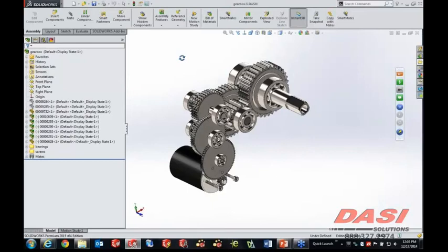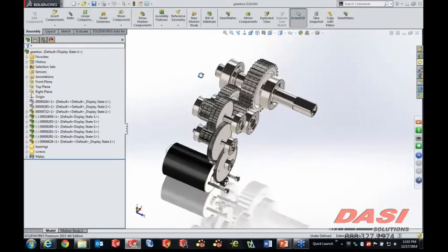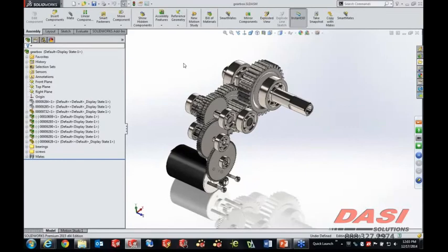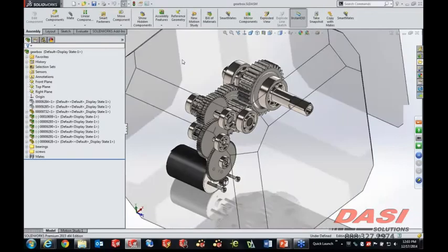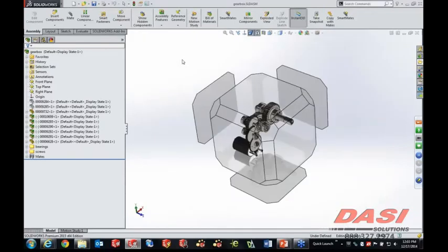So on screen, we're looking at the SolidWorks assembly currently. And when a SolidWorks assembly is on screen or a part file, we've had this tool that we added a couple of releases ago called the View Selector. And you typically get there by holding your control key and hitting the space bar, and it brings up this cube that shows around your part or assembly.